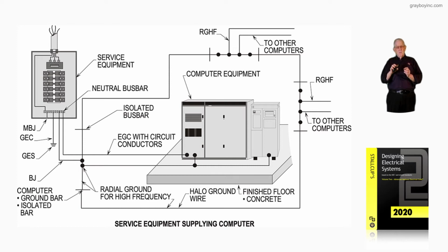And then the equipment ground that is sized off of the breaker in the service equipment is routed over and connected to the sensitive electronic equipment. Any noise that might be generated over that equipment ground will in most cases kind of choke it down about 3/4 of the way, 2/3 of the way from the sensitive electronic equipment routed toward the service equipment. It'll choke out the noise in such a manner it doesn't become a problem.